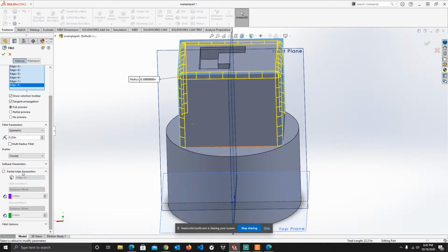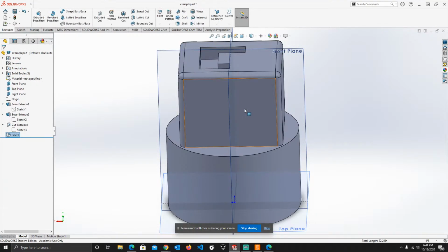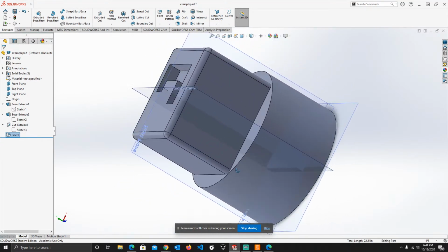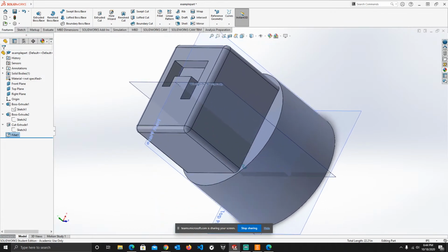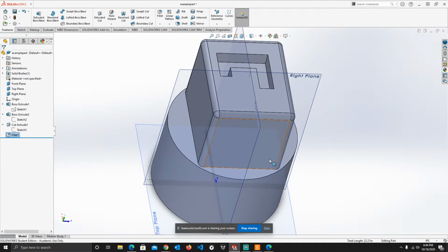Okay, there's other things here that you can use as well. I haven't really touched them, so unfortunately I wouldn't be able to help with that. That will be something more advanced. But as of right now, for our purpose, fillet just works completely perfectly fine. So let's just click OK. And just like that, now our cube has a fillet on all of those parts that we thought were horrible, that we shouldn't have a sharp edge. So, okay, we touch fillet.